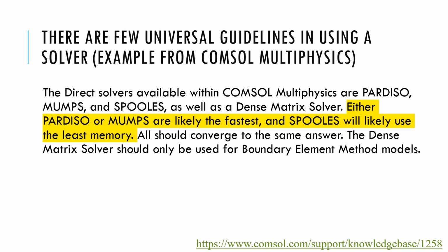So just to make the point, I have copied here a direction from the software COMSOL Multiphysics, and as we could guess, they're saying several direct solvers are available within COMSOL, and they're saying either Pardiso or MUMPS are likely to be the fastest, and SPOOLES will likely use the least memory.